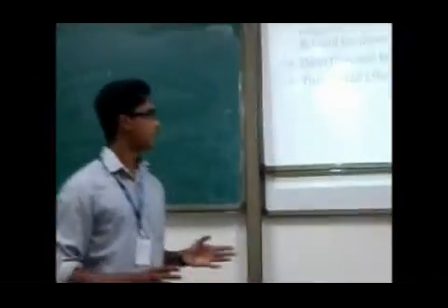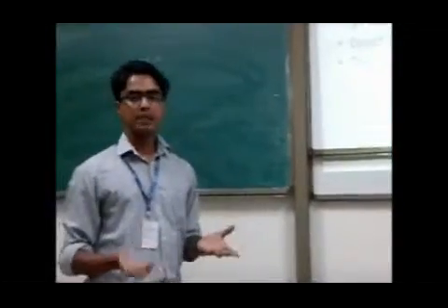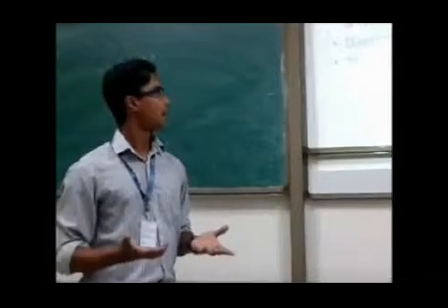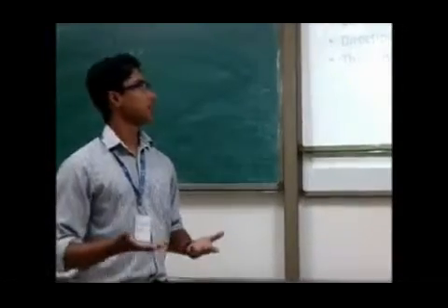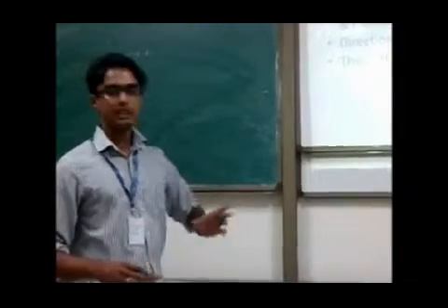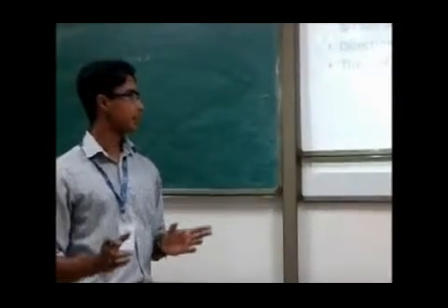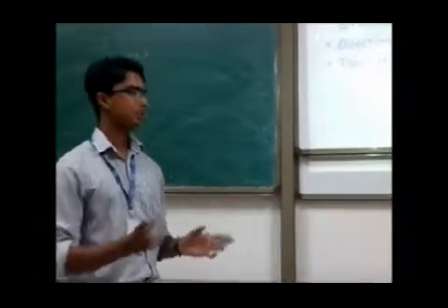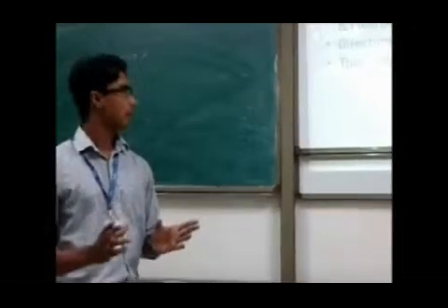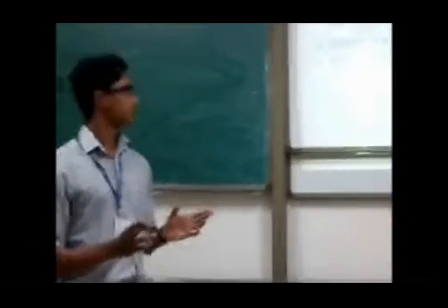And now I would like to explain the principle of the Hall effect. Long back in 1879, Edwin Hall first observed the Hall effect. What he did is he took a rectangular slab to which he applied a perpendicular magnetic field, and he applied current also in the direction perpendicular to the magnetic field. When he measured the potential across the conductor, I mean the rectangular slab, he found that a potential is developed across the conductor. That potential is known as the Hall voltage.